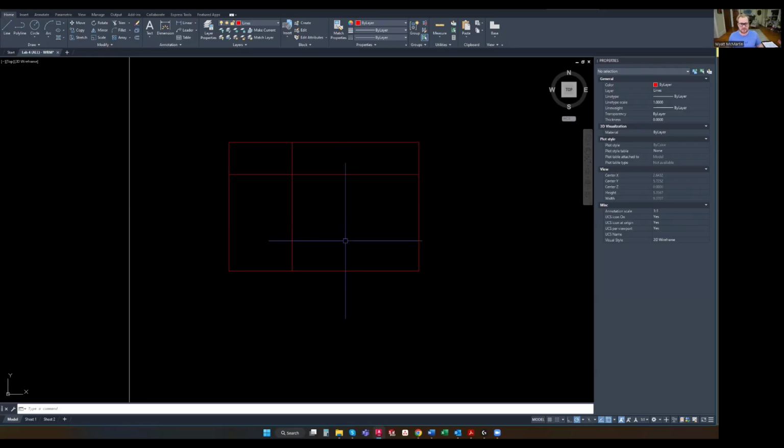It's more of a feature that allows you to be more specific of where you place the beginning of a tool, like a line or a rectangle, where you place that first base point. It's called displacement. So what we could do is grab our line tool, just like this, or click L, enter. And now hover over this lower right point, and it'll say endpoint and give you a little snap icon, a little square. So I just hovered, I didn't click.